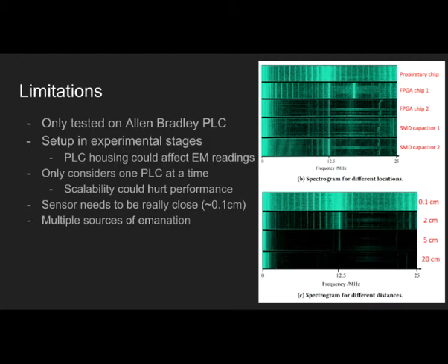And also, if you notice in the first image of the setup, it's a very experimental setup. First of all, you have the PLC all opened up, which is not how it is in the real world. And you have the sensor really close. If you look at that bottom graph, you can see that it's not getting any results when it's only 2 centimeters away from the PLC chip itself. So it has to be really close, and in a real-world situation, that's probably not possible. And since it's so experimental, potentially something like the PLC housing could affect the EM signals.